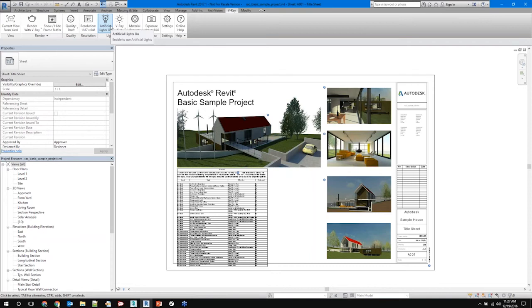Pay close attention to your lighting families, especially if you get them from manufacturers. Whether they're nested families or not, you'll need to make sure that you pull those light elements down to the bottom side of the geometry itself for the lights to work correctly. And then always look for a manufacturer's IES file that matches your design intent. And then you can get really great results with interior lights that way.